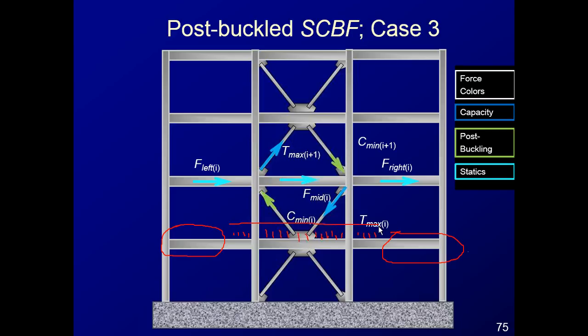And also, it does have a little bit of an effect on local chord forces. We're not getting into the design of the diaphragm here, but the way that you get axial forces in your chords is to have shear adjacent to those chords.